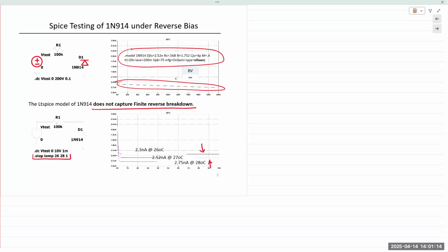If you've used a digital thermometer, cheap ones, expensive ones, there are two diodes in there, and there's a circuit in there. I can show the circuit outside of class if anyone is interested. But you create a circuit using two diodes, it measures the reference temperature, and as the temperature changes, the diode voltage changes. And again, because the relationship is very linear and fixed, you can calculate the temperature as a function of the voltage.